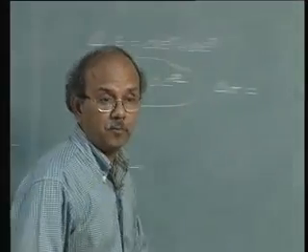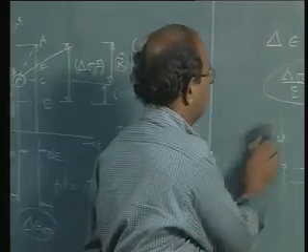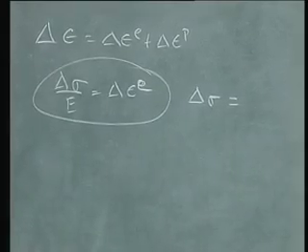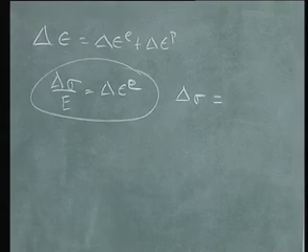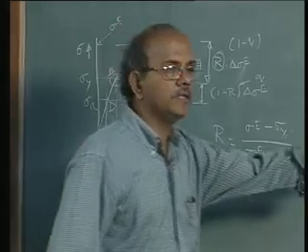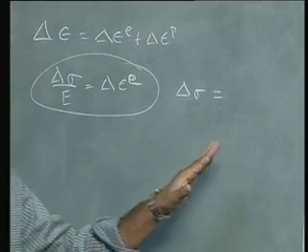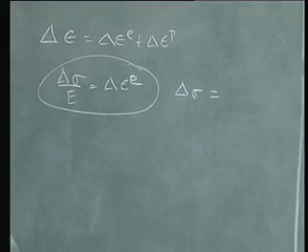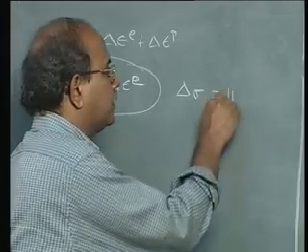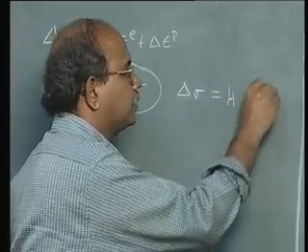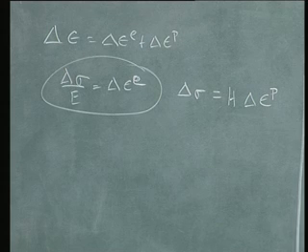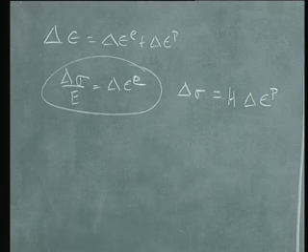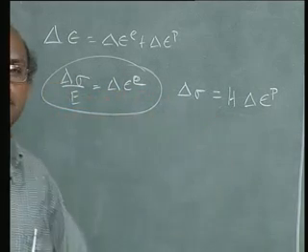And why do we need epsilon p? I hope things are very clear now, that we need epsilon p so that we can predict these strain hardening parameters. Delta sigma can also be written in terms of what we called the plastic modulus h. So that can also be written as h into delta epsilon p. Is that clear?